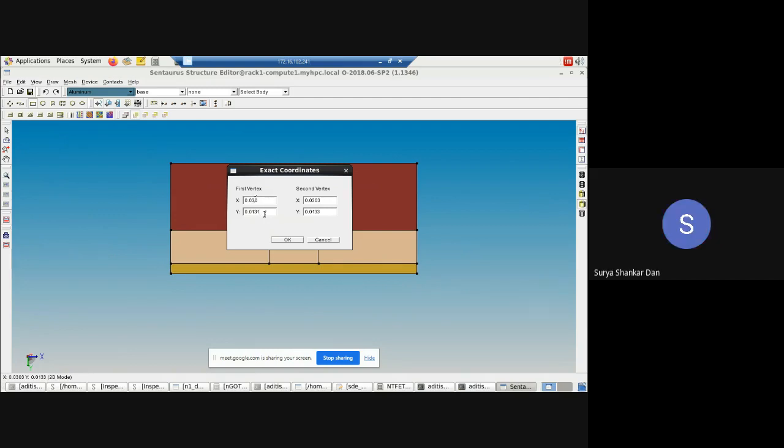Students, you can see that Aditi has chosen aluminum for the gate material. Those of you who were there in the physics and modeling of microelectronic devices, recall that aluminum has its work function very closely matched with the electron affinity of the material used in the channel, silicon germanium or silicon.